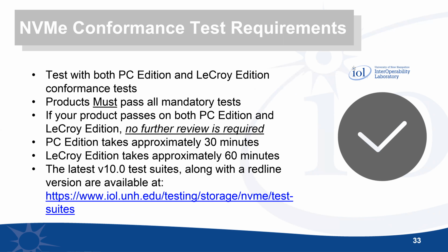The testing that happens would be for conformance devices for PCIe, and of course you can use the PC edition or the LeCroy edition. All tests that are mandatory must pass, very similar to all the fabrics testing that we just went over. And of course, we give you some times roughly that it takes to perform these tests. Obviously that could vary depending upon the product. And then at the very bottom, you have the actual test suite, the link to the test suites again. So this is probably like the second or third time in the presentation you've got a link to the test suites. So please go out, take a look at them. You can get an idea of what we will be testing at the next Plugfest.